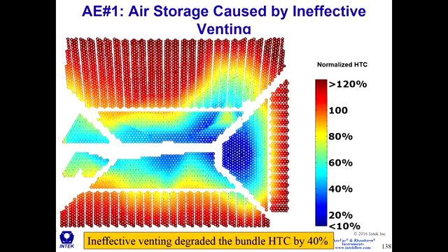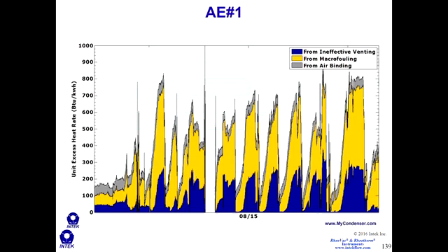to improve its performance. After doing the study, we identified this airbound zone here, and we were able to use the techniques that I showed you on previous slide, the water-to-air mass ratio versus cleanliness curve, and the air binding performance profiles to determine how much excess unit heat rate was a result of the air binding, as well as macrofouling and ineffective venting.